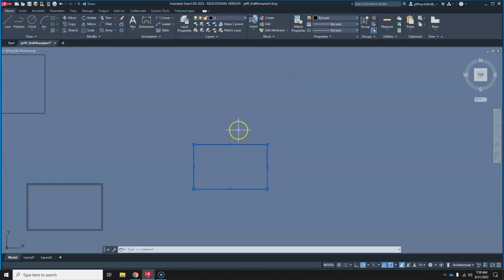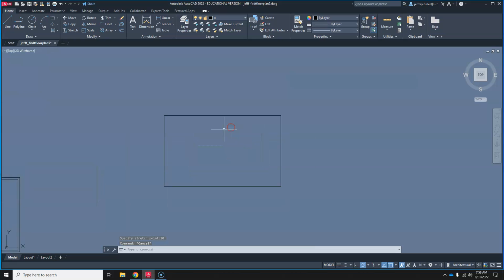All right. Next thing I'm going to do is an offset. So I have to kind of understand walls a little bit. In this case, we have to add up all the different materials of a wall, and we'll go over wall structure in more detail later. But for now, if I add up all the materials for the wall, it's going to be 9.5 inches. That's how thick the exterior walls are going to be.